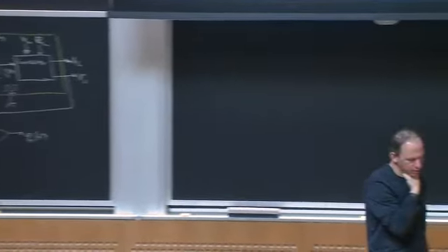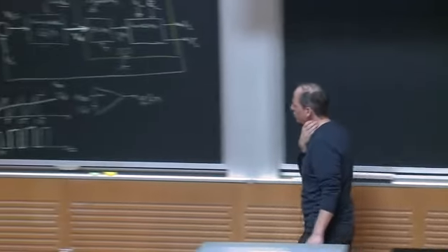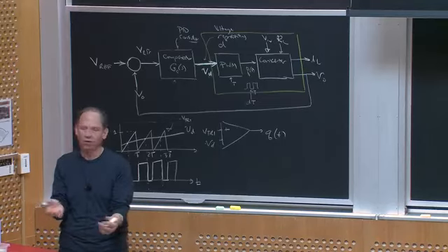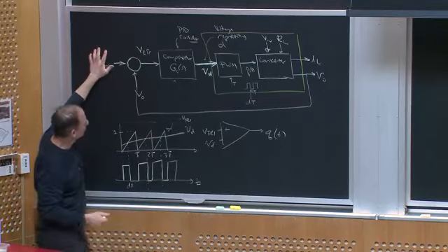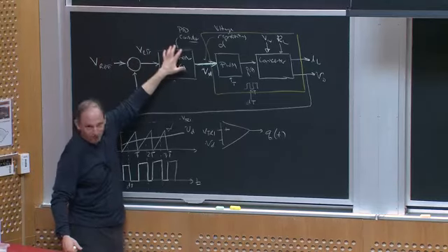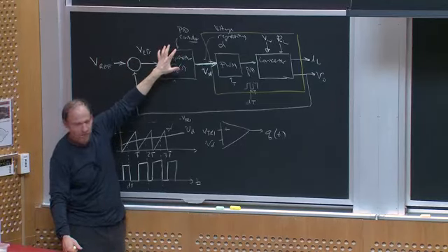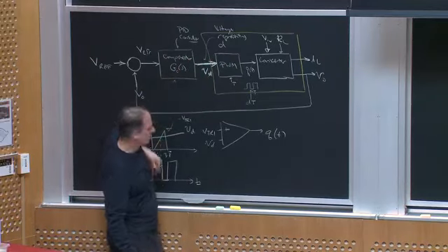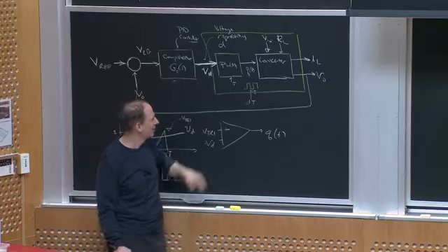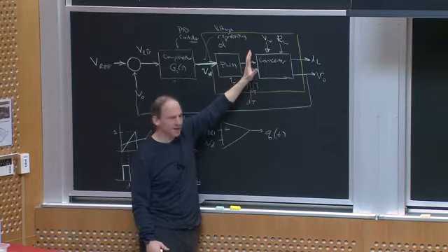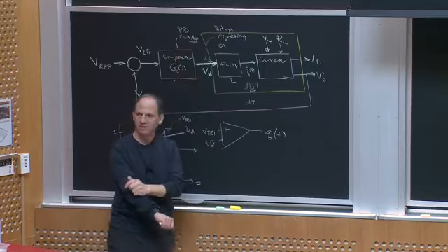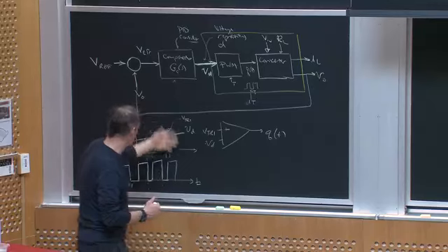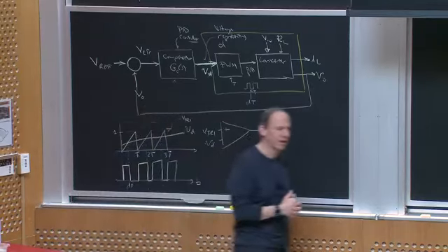All right, so that gives me a way to implement this. And I should say, by the way, that if I go buy a PWM chip for a typical DC to DC converter or controller chip, I'll usually get a reference, some kind of error amplifier, op-amp, and other things to generate the compensator. I'll get the PWM chip, and in fact, this triangle also serves as my clock, so I can set the clock frequency, I can set T. And then, maybe it gives me a gate driver. So I'll kind of get all this stuff in one chip very often for a simple design. Okay? Of course, you can also do a lot of this stuff digitally these days, depending upon what kind of processor you use.